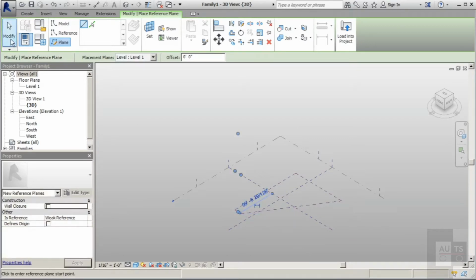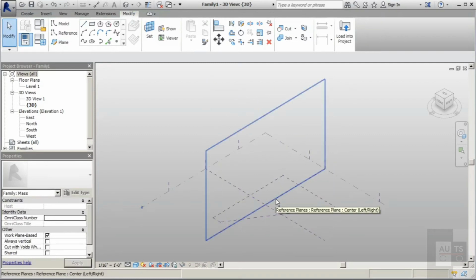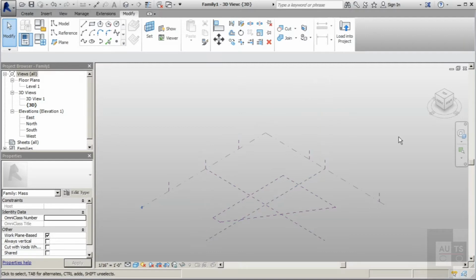and we'll close that off. So if I wanted to, I could select all these and create a simple surface, but I don't want to create a simple surface. I want this to have a nice elegant curve to it and a sweeping look. So to do that, we're going to set some reference points, and also we're going to be working with some splines, and I'm going to show you some really cool ways to create forms other than just using your basic extrusions or sweeps. So we're going to start working with some of our reference points.